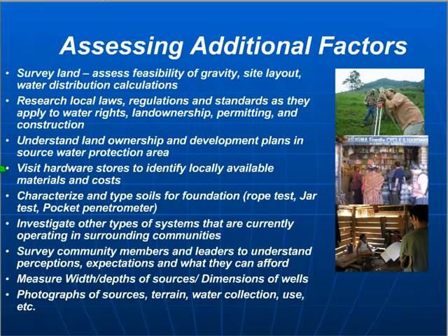It's also really important to visit hardware stores so you can make sure that any material that you're using is locally available. That's a flat-out requirement of any EWB USA project, that all materials are locally available. And so you need to be aware of what materials are, and this is especially important with any kind of pump option or treatment option. If it's not locally available, it's going to be really hard to fix if something goes wrong, and therefore it's not going to be sustainable.